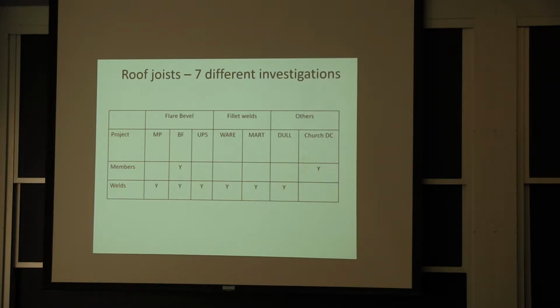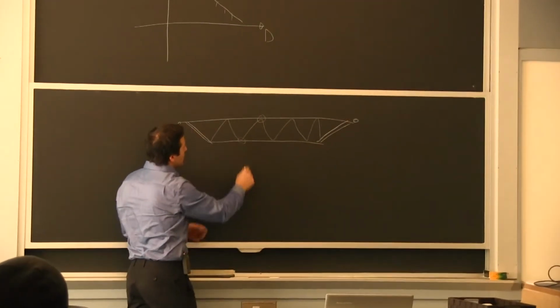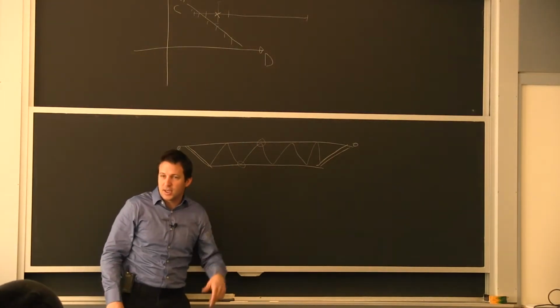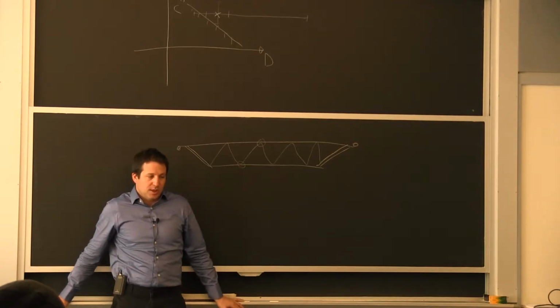So if I have just a very simple roof joist with a top chord, lower chord, and then I have this first diagonal. This is the diagonal that's going to carry the most tension each side. And then I got some simple support. This is the simplest structure I can come up with. And then I have a bunch of little diagonals that if I'm failing a joint here, it should be all right. If I'm failing 2 of them, then I'm starting to lose stability. I could have sagging of the joist, or I could have a partial collapse, depending on what it is.